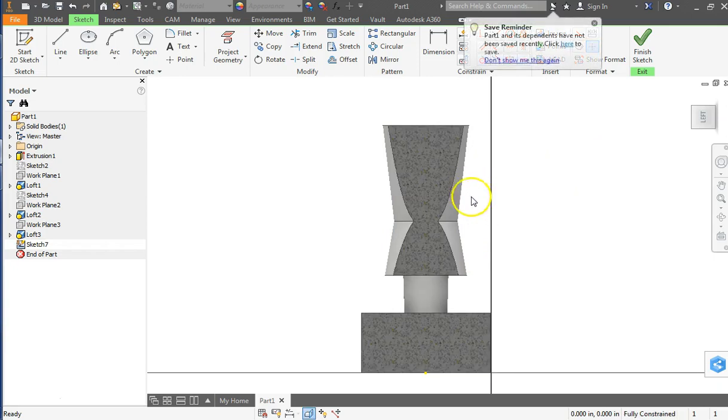So our goal here is to basically either extrude cut away some material on the top, or the way we did it with the male is we use the extrude intersect. So we created a profile that included the area we wanted to keep, and when we extruded it, we said only keep what's inside this. Okay, so I'll do that again.